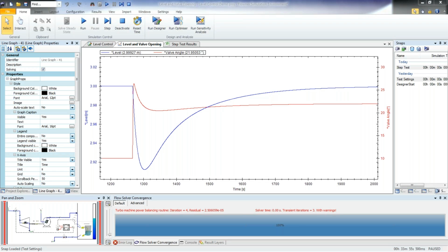We also look at integrated control and process performance assessments. So we can look at accident scenarios, as I mentioned, or what-if studies to try and prove that our plant is safe. Basically, in very strict industries such as the nuclear industry, this is a requirement. So you need to investigate all of the possible failure scenarios and prove that there are mitigation measures / control measures in place that can now handle these scenarios and ensure that they're properly dealt with and that the plant remains in a safe state of operation.